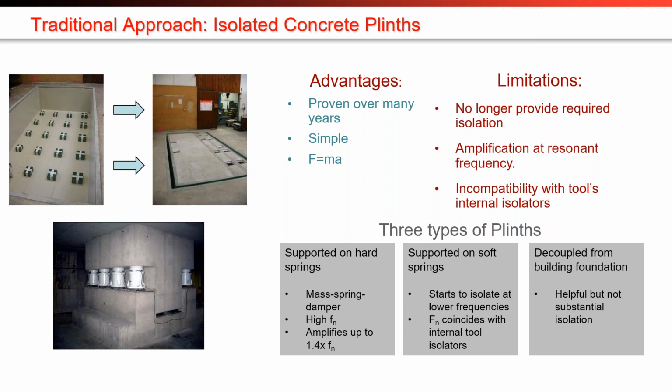And finally, a really critical reason is that all the ultra-sensitive instruments already have a vibration isolation system built in, something fairly sophisticated, typically a low frequency air isolator to filter out high frequency vibration, but amplify at its resonant frequency.